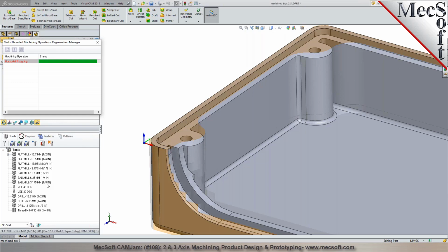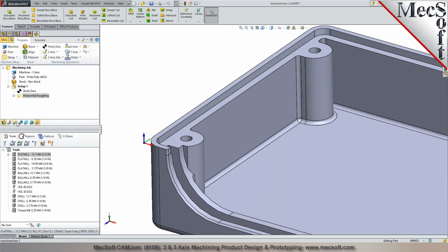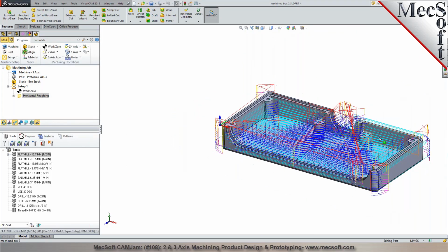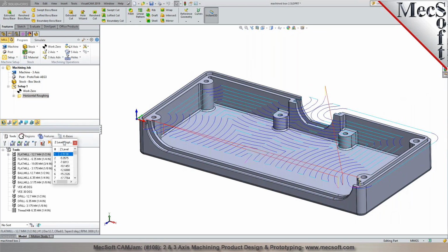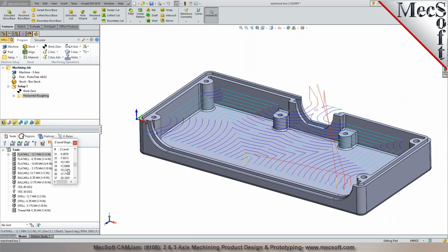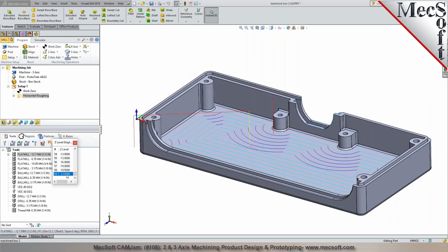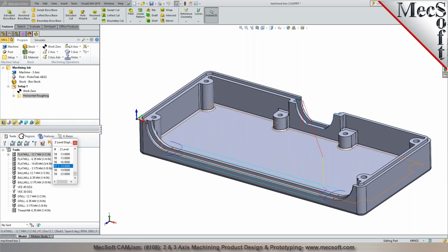Okay. Now, will that apply to all the flats like that? All the flats, I guess. These over here, it'll do the flat over here. Okay. Yeah, all the flats. If you actually take a look at the toolpath in here, as you step it down, you'll see it goes and cleans up each of the flats down at the floor right there. Yeah, I got like 5. There's like 5 flat levels on here. Yep. So it automatically takes care of each of the flats as well.